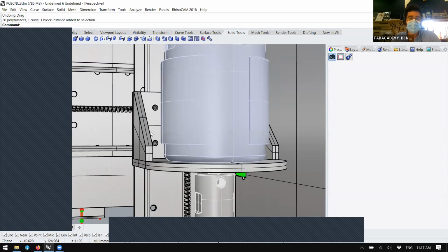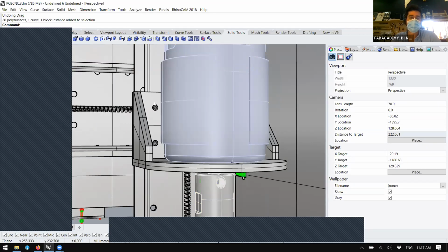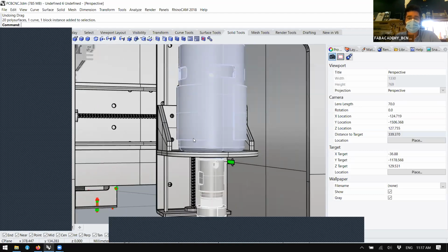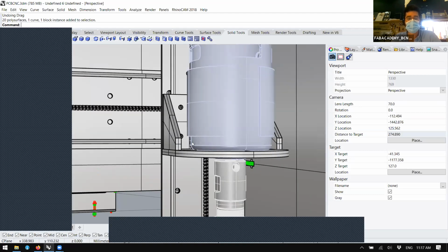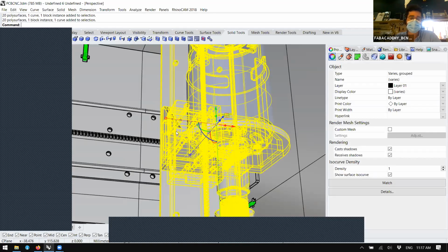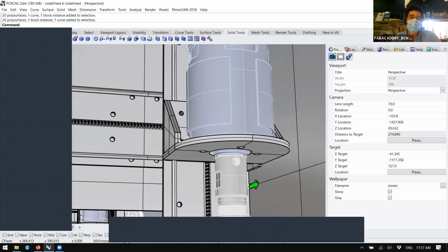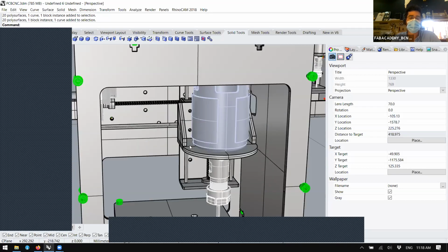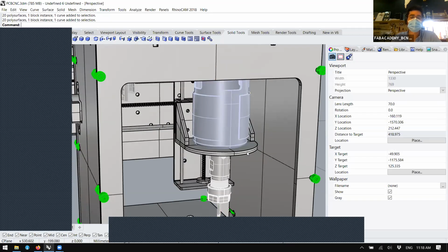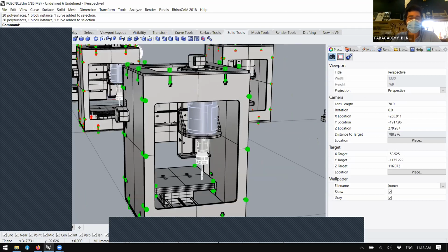For example, the holder, we have an initial design, but if you go to the latest version, this is like 3 times thicker. Why? Because we measure this. Okay, with this geometry, what technologies can we use for manufacturing? This method of acrylic will imply having 2 screws here to fix this plate to this little plate, and to have another one in this one. So it will increase a lot of complexity to such a small part. So okay, for this piece, it's much better to use a mold or to 3D print the part directly. You can make it sturdy enough.